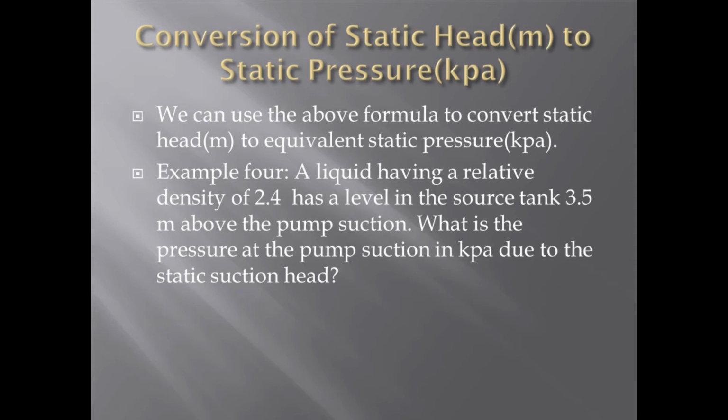Example 4. A liquid having a relative density of 2.4 has a level in the source tank of 3.5 meters above the pump suction. What is the pressure at the pump suction in kPa due to the static suction head?